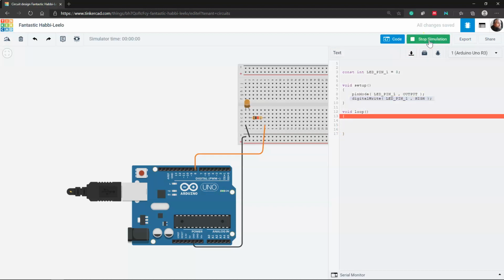So we run it again, and you can see it here. Sometimes in your setup, if you want lights to be on at the very beginning of the startup of your actual project, you can do it up here. So we got digital write. Again, we've set it once, it's turned it high, told it in the controller, the program's moved on, the internal state of the controller is keeping the power going along here to actually be high, and boom. Okay, we'll stop the simulator.